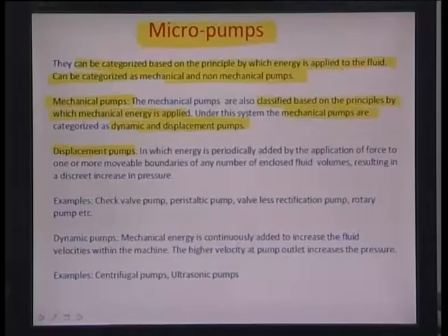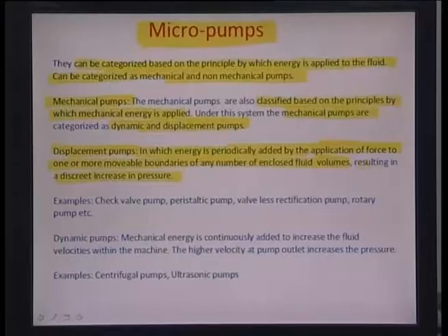Displacement pumps are those where energy is periodically added by the application of force to one or more movable boundaries of any number of enclosed fluid volumes, and this results in a discrete increase in pressure along the direction of valving, and the fluids keep moving in that particular direction.